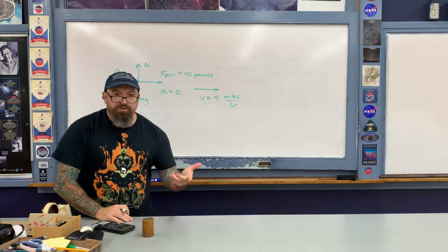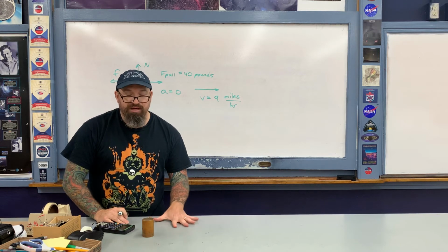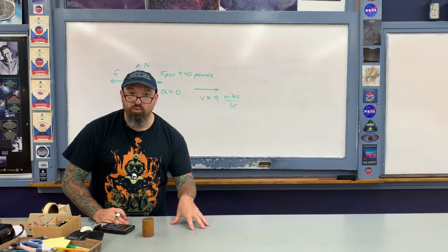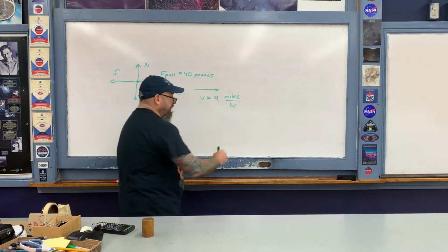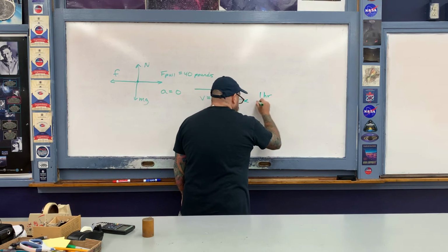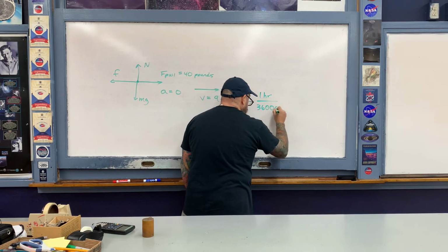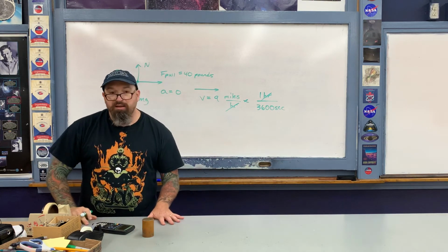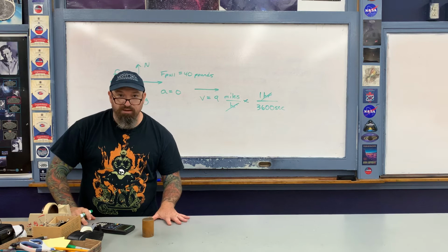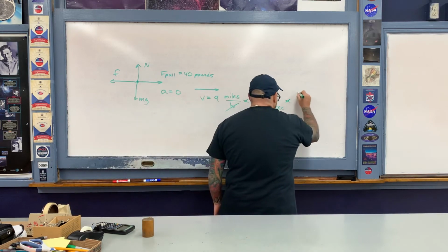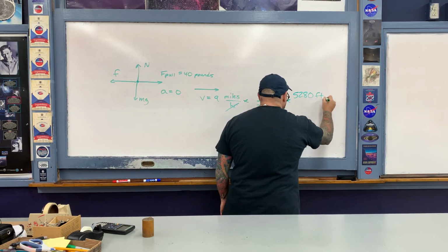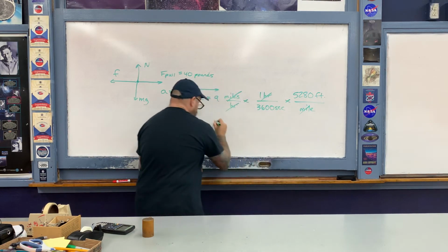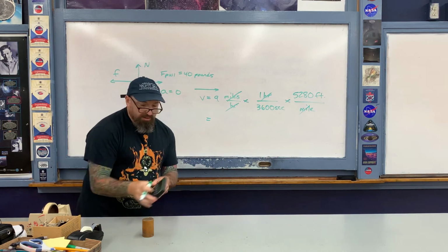Okay, what I need to do first here in order to calculate the instantaneous power output of the horse is convert the miles per hour into the base units, which are feet per second. So first of all, hours. 1 hour is equal to 60 times 60 or 3,600 seconds. So I'm going to convert hours to seconds by doing that. And then there are 5,280 feet in a mile. So let's now go ahead and multiply by 5,280 feet per mile. And then miles cancels here and here, and we'll end up with a speed in terms of feet per second. So let's go ahead and convert it.